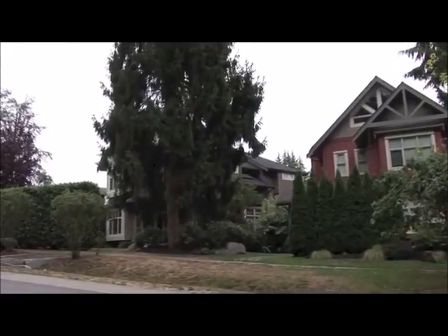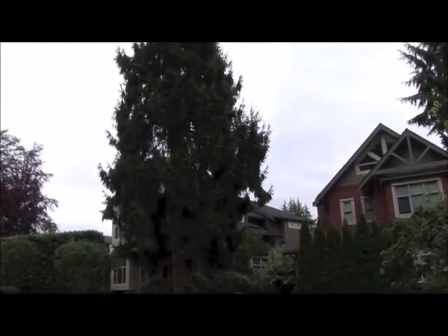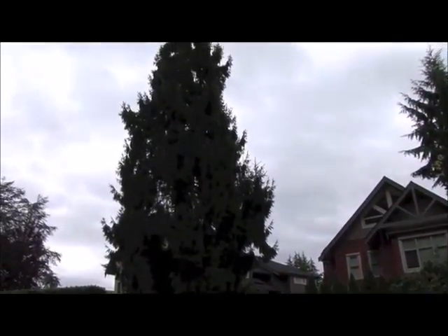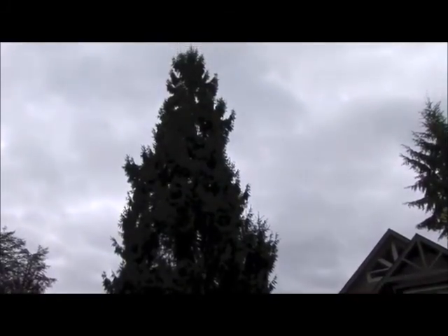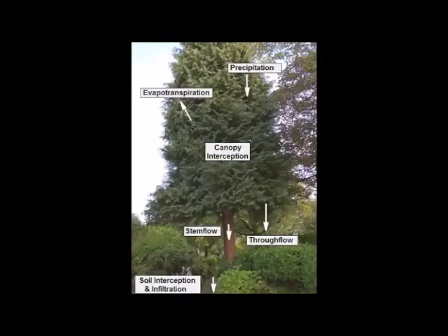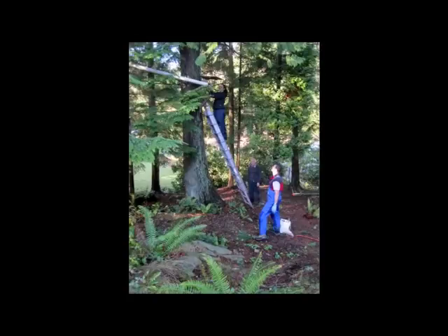In addition to thick topsoil, you can plant trees. Urban trees are very important for stormwater management. Rain is intercepted by the leaves in the tree's canopy. This reduces and slows rainfall that would otherwise become runoff. Water also evaporates from the canopy back to the atmosphere.